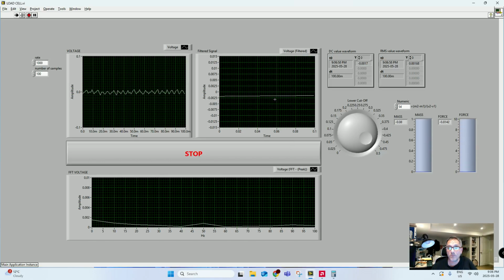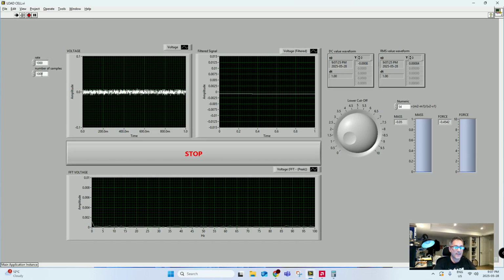But to appreciate this more, I had to expand the low pass filter up to 10 Hz. Then to visualize better, for example, 5 cycles per second, I had to increase the window. Otherwise, I'm not going to see 5 cycles, but just a fraction of it. So I increase the number of samples in order to have a synchronous sampling, right? And then I push 5 times.